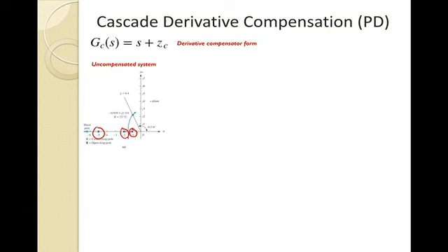And then once we do some algebra to get it out, I'll write it in its final form right here, where we have our K in the numerator. And then it's going to be an S cubed plus 8S squared, and then plus 17S, and then plus 10 plus K. Okay, so this would be our closed loop system.